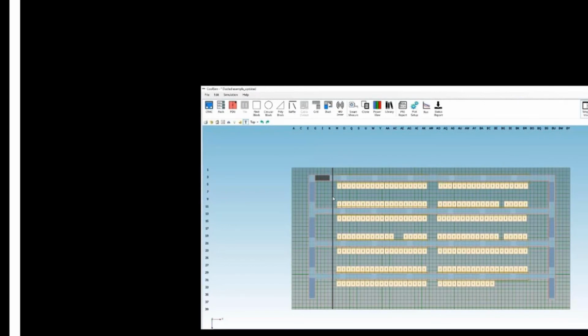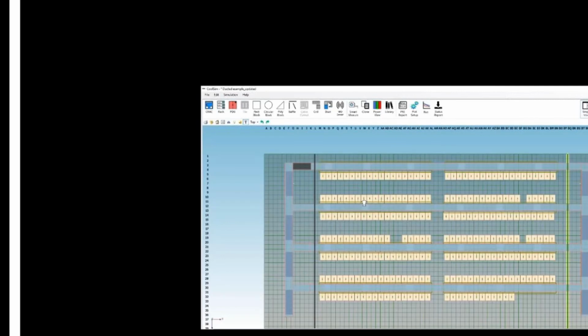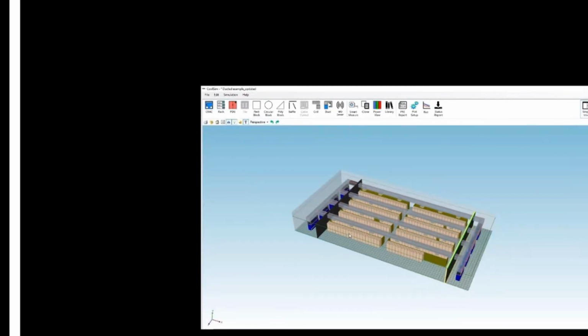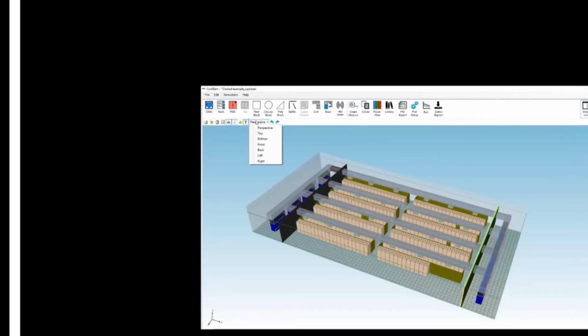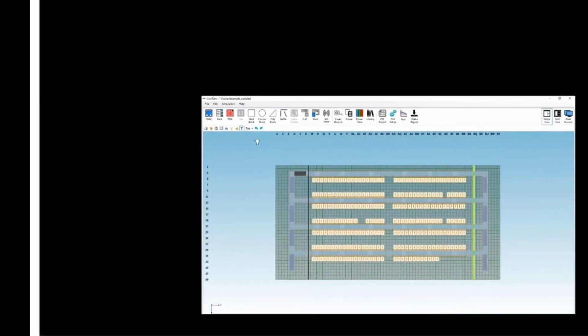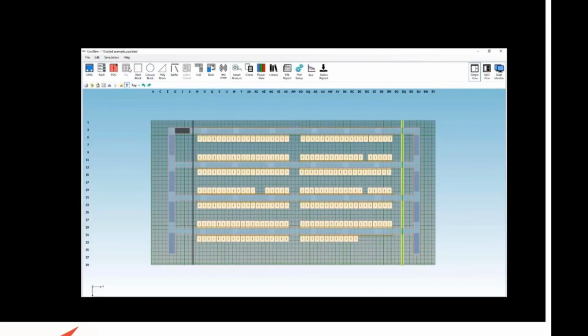Notice the fluid block is going right through the wall. I'm going to Control C over here, Control V. I don't need to worry about punching a hole because the fluid block has priority. It'll blow through anything. You can get it to go through blocks, baffles, racks. It goes through anything. Fluid block has priority and can and will go anywhere. So here I'm just laying this thing out, and I've got my 2 blocks in place.